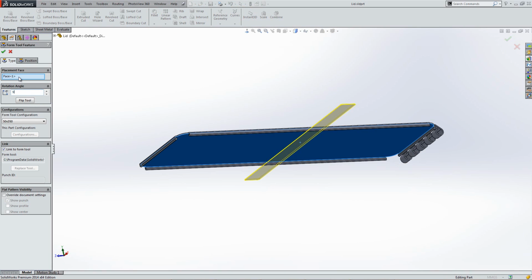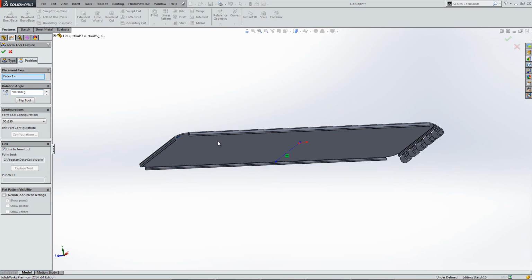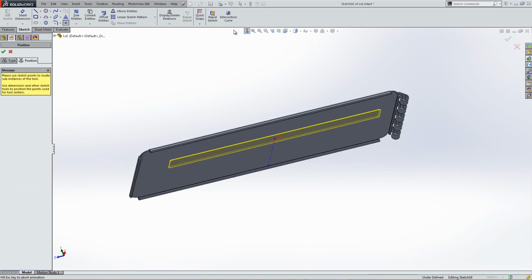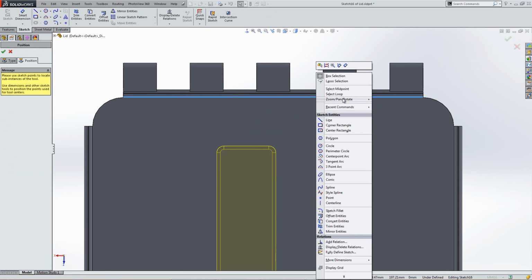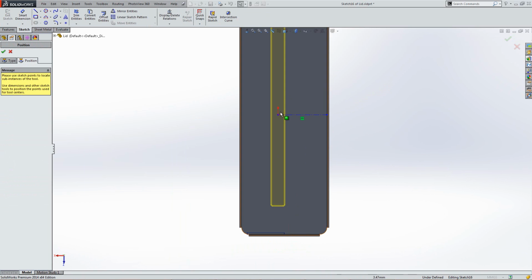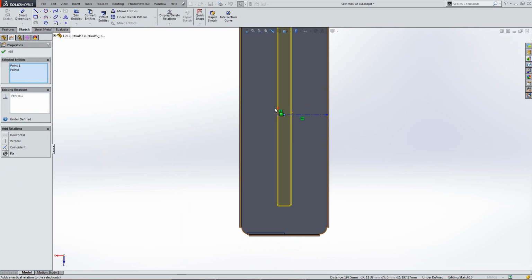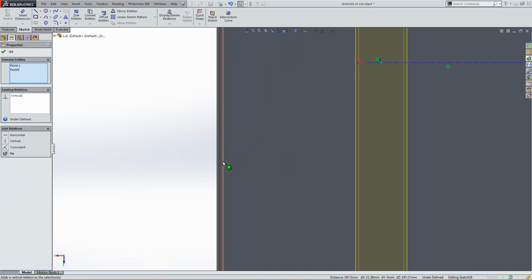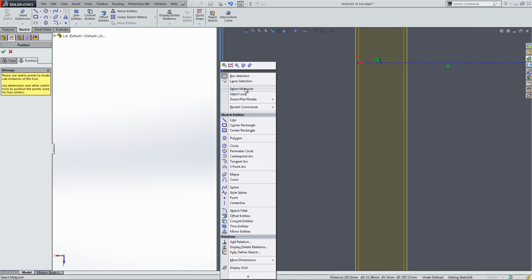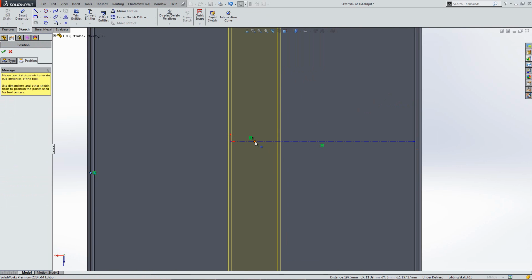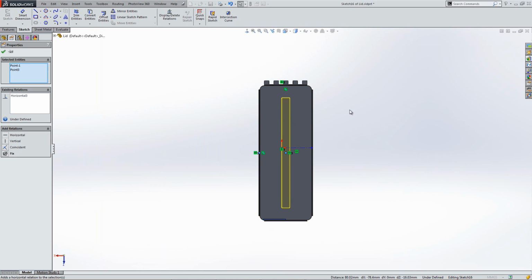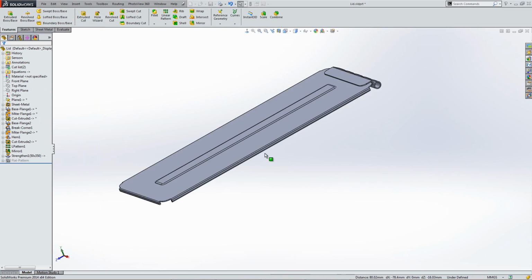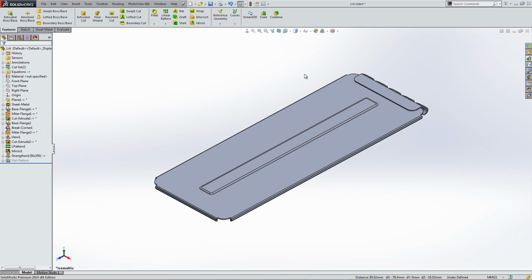And I'm going to rotate that 90 degrees. So just like before, we'll go into the position, we'll just go normal 2. There we go. Select the midpoint of that and then the insertion point, and we'll make those vertical. And we'll do the same for this. We'll just select that midpoint, and we'll make those horizontal. Now our sketch is fully defined. We know it's in the center. We can OK that and OK our position, giving us our insertion on the top,